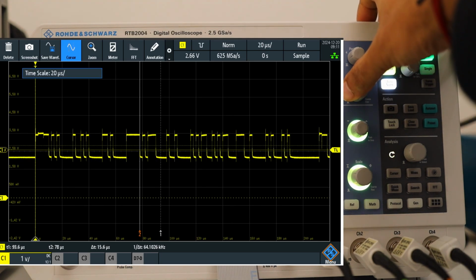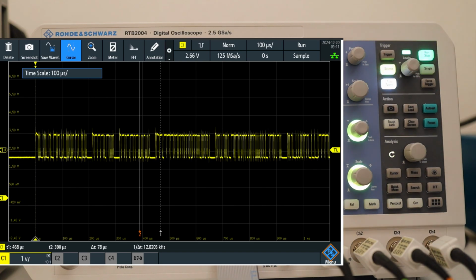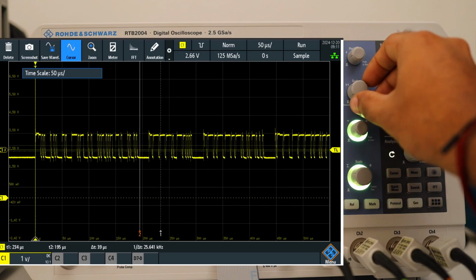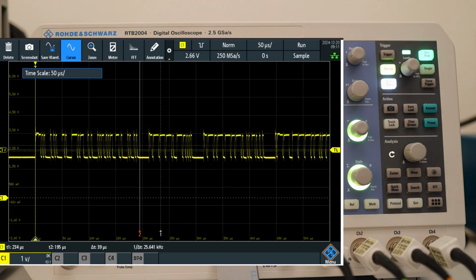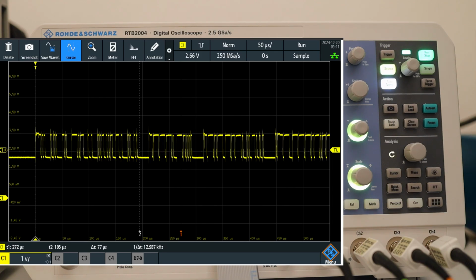See, there are at least 2 different packets available, because you see sometimes it flickers in the beginning. It doesn't flicker later because this is rock solid. Here it's rock solid, but from here up to here it does flicker a bit. So this kind of situation can be filtered out or mitigated using a bus trigger. We will try to find out if we can set up a bus trigger there, and what we can do about it.